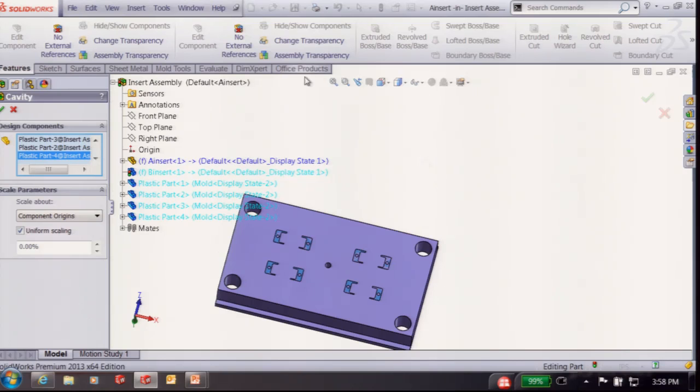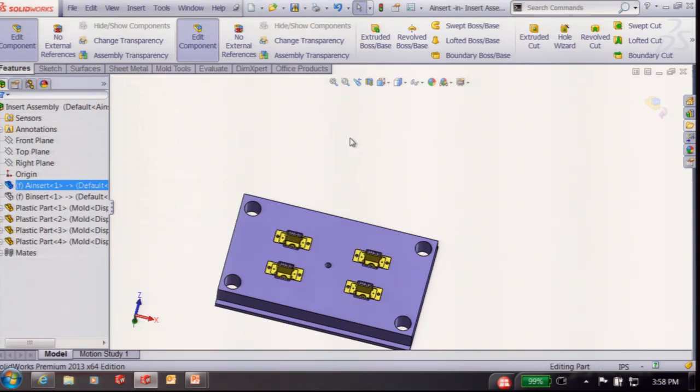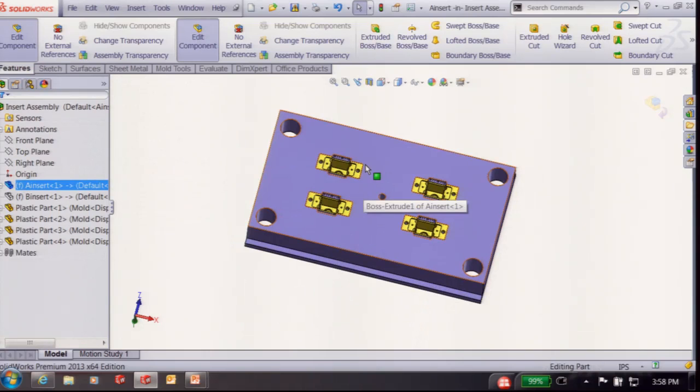That's a great subject. But when I use that, there's options to scale if I want to. I typically like to scale on the part, make a configuration of the part, scale it up, put it into the assembly, and do this step. So when I hit the green check mark, I've got my A side. And everything's based on the B side, so whatever I'm using for shutoffs and parting surfaces there is transferred over to the A side. And so that's typically another way I use a lot to design molds.